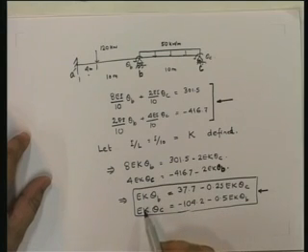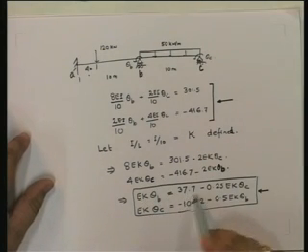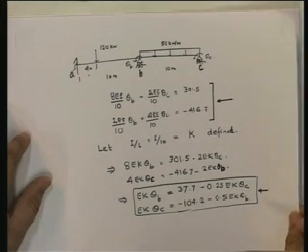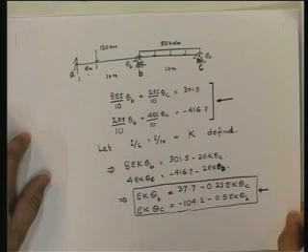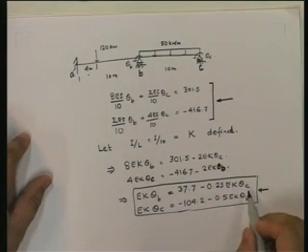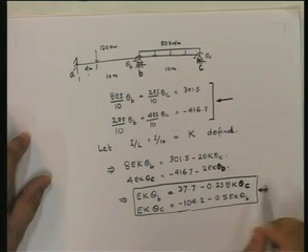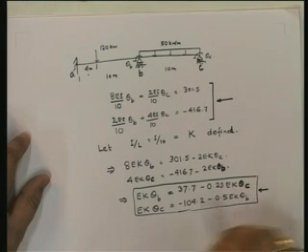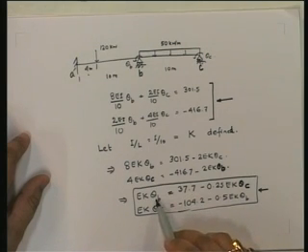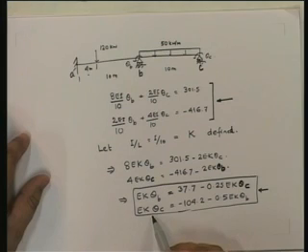So essentially when you do this, this becomes EK theta B is equal to 37.7 minus 0.25 EK theta C, and EK theta C is equal to minus 104 minus 0.5 EK theta B. Now these two equations I am going to solve iteratively. How am I going to solve iteratively? Well, initially I will assume that theta C is equal to 0, so EK theta C is 0. If EK theta C is 0, that means EK theta B will be 37.7.